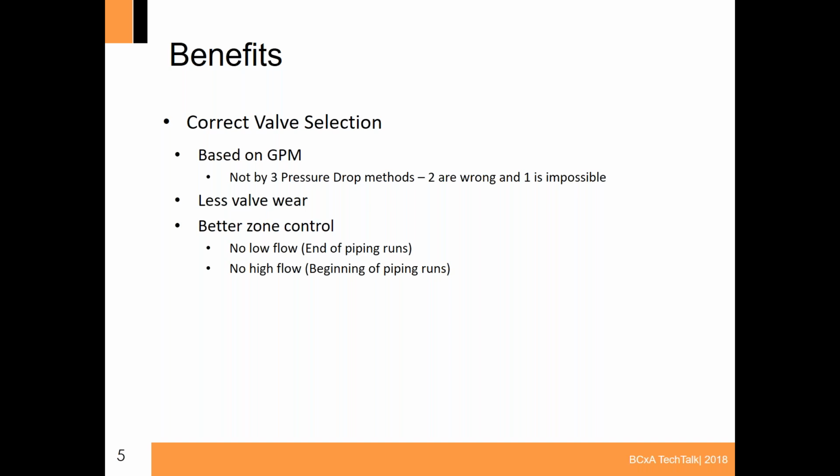And as we adjust that pressure in the system, the flow through that coil, especially ones closer to the pump, changes, and now if we're pumping more water through the coil, we're delivering more heat content, or taking away more heat content if it's a chilled water coil. And now that control valve needs to adapt to that and close down. Whereas in a pressure independent valve, we're adjusting and compensating for that pressure and delivering the same GPM depending on the position of that control valve.